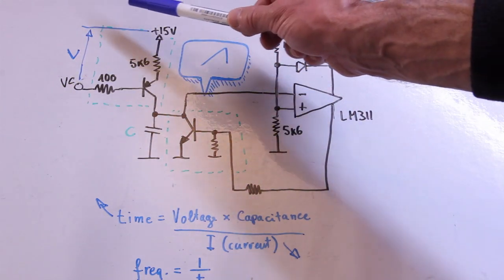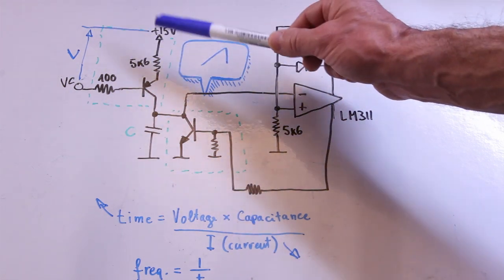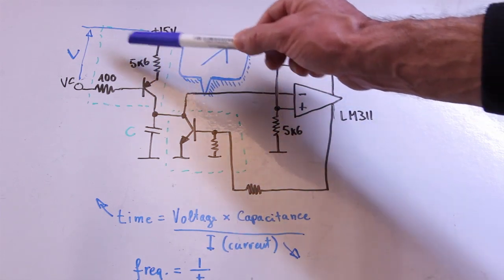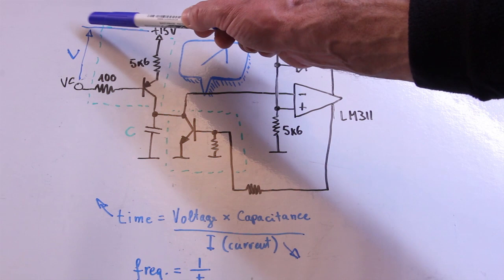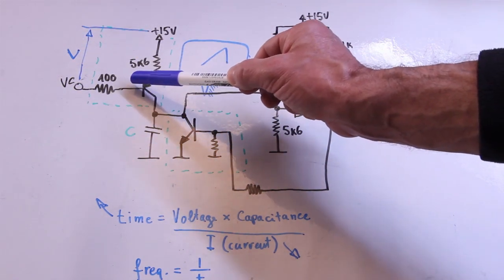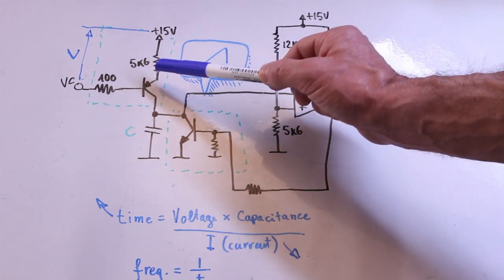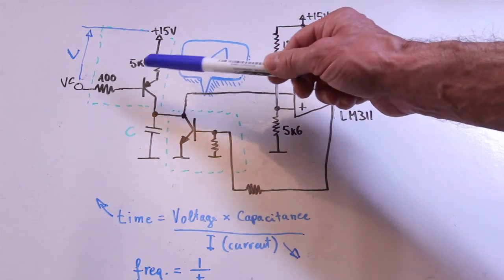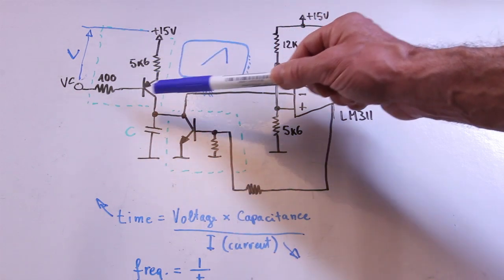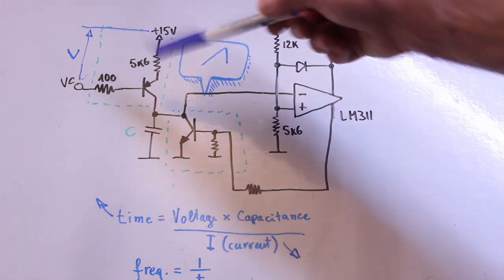And for those among you that don't know how this current source works, let's assume that the voltage across this resistor here is given by this voltage, the voltage between the positive rail and the base of the transistor, minus the voltage drop between the base and the emitter of this transistor. And I will make a video with more details to understand how constant current sources work, including the one with a single transistor like this.